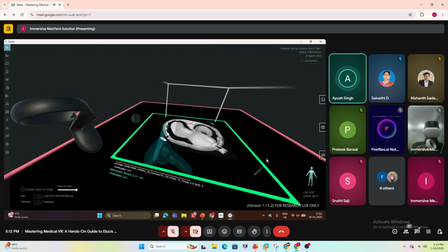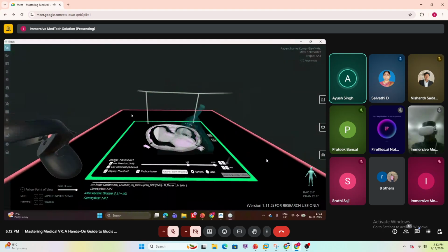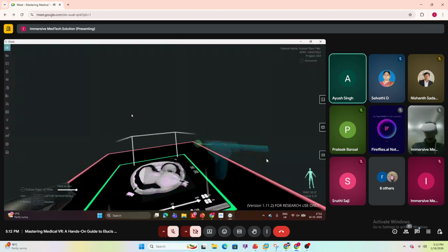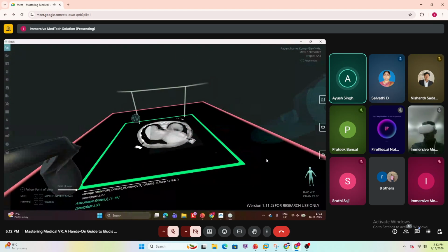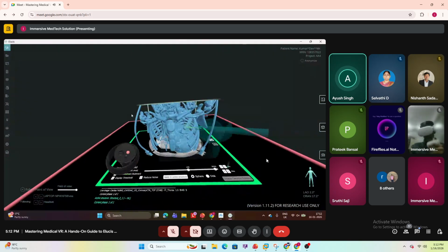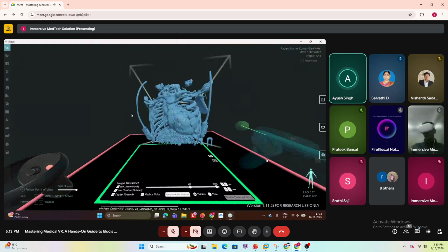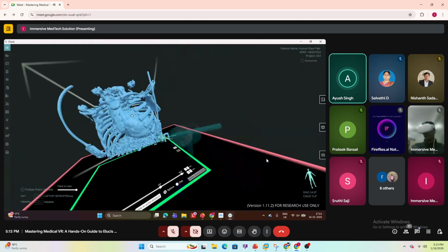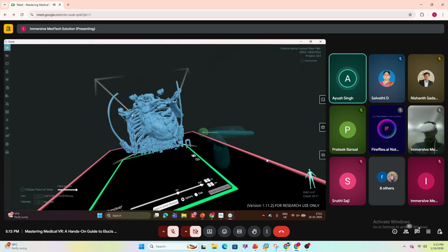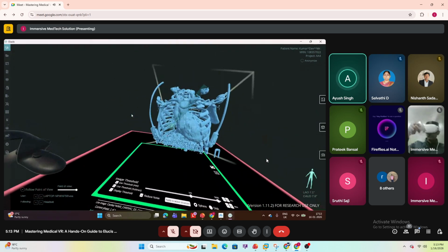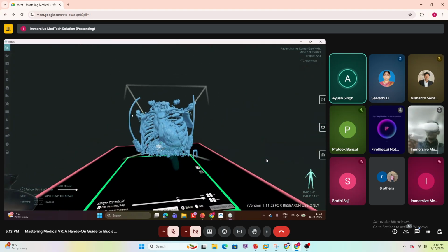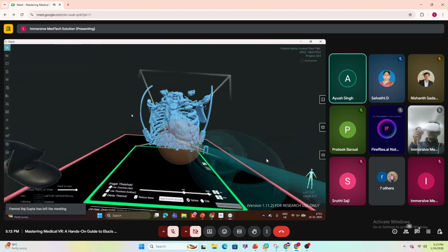Before that, we can also click on reduce noise to remove the small noise that is present, which might be metal artifacts or any distortions in the dataset. Once it is done, we need to click on apply active structure. This is the initial and easiest way to segment the whole anatomy within seconds. So we have done the quick segmentation for that. But there are many parts present which aren't required for us. To remove, for example, the ribs and the wires, how can we do that? We can click on subtract, and if we move the particular head backwards, it will increase the brush size.